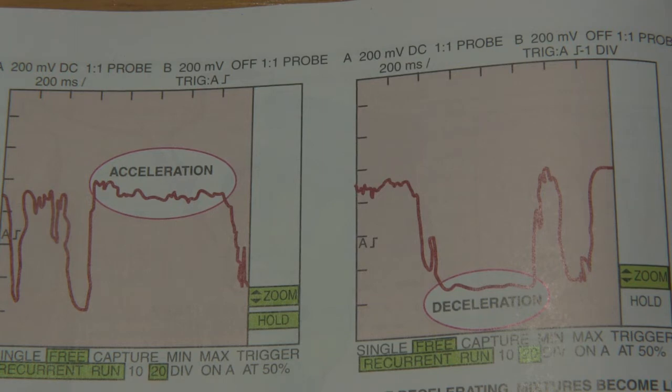It's pre-programmed that when you go to full throttle, it's going to assume, now that's the issue, it's going to assume that you have a healthy running engine, good spark plugs, good fuel injectors, good air filter, good fuel filter, good fuel pump. It's going to assume all those things are okay, and it's going to adjust the fuel delivery, the pulse width of the fuel injectors, to a predetermined millisecond on time to give the engine what the engineers call for, whatever they came up with for air-fuel ratio for best performance.